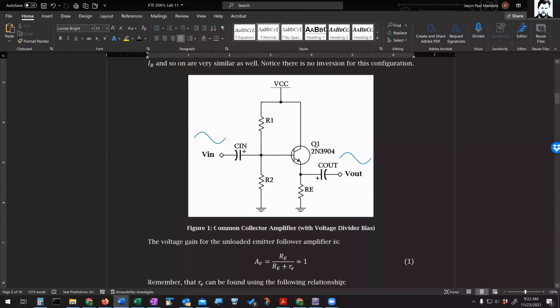And again, the word common in the naming means that point basically becomes a reference point. This amplifier is called a common collector amplifier, and here's the collector. So what's common about this collector? Well, we know that when we're doing AC analysis of this circuit, this DC source looks like a short, like a connection to ground. So in that way, it's almost like this collector is actually grounded from the AC circuit's perspective. That's why it's called common collector.